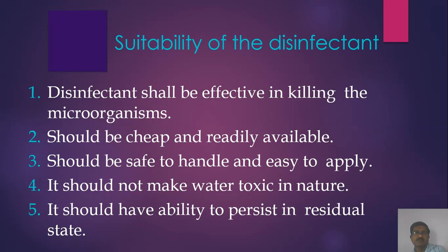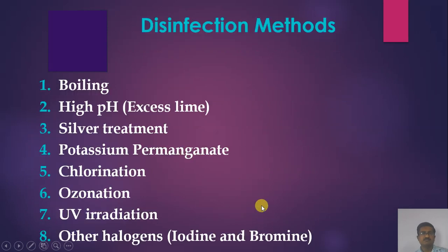Suitability of disinfectant. The disinfectant shall be effective in killing the microorganisms. It should be cheap and readily available, should be safe to handle and easy to apply. It should not make water toxic in nature. It should have the ability to persist in a residual state.